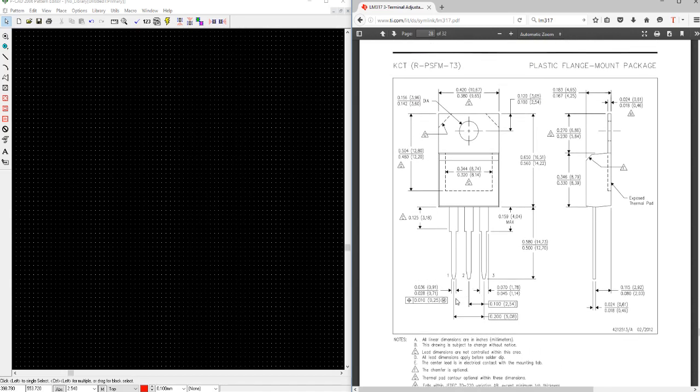Okay, so from that, we can see here that we are sitting with a 0.1 inch pitch or a 2.54, or we can say it's a 100 mil pitch. So we know that these pads need to be 2.54. Now, I said to you guys that in symbol editor we work in mils, because our schematic we draw in mils on a 100 mil grid. In PCB footprint, I would suggest we stick with millimeters.